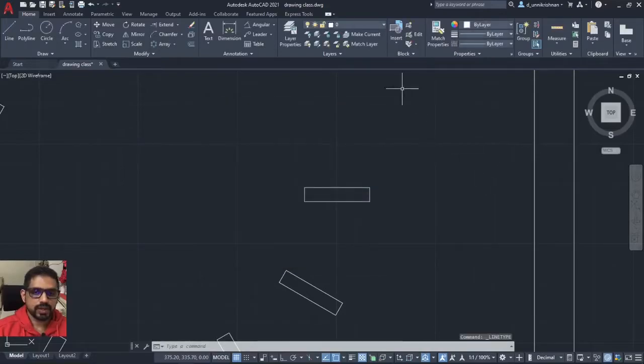Okay, now click OK. Now again going back here, select it, change it to hidden lines, and as you can see here the line has changed its type. Now it is no longer the continuous line, it is a hidden line, type E line. How do I change the line thickness? I did change the line thickness. If you see here, the property shows that it is 0.5, but it is not depicted in the drawing. How do I change it?